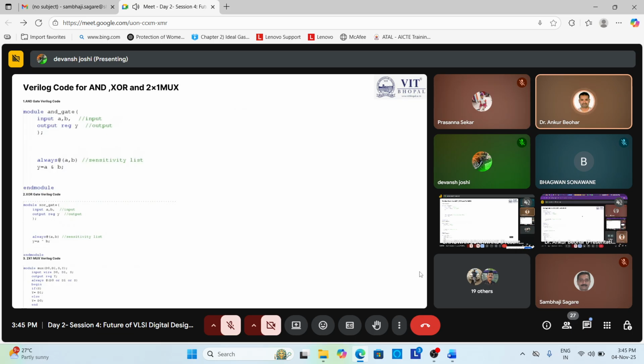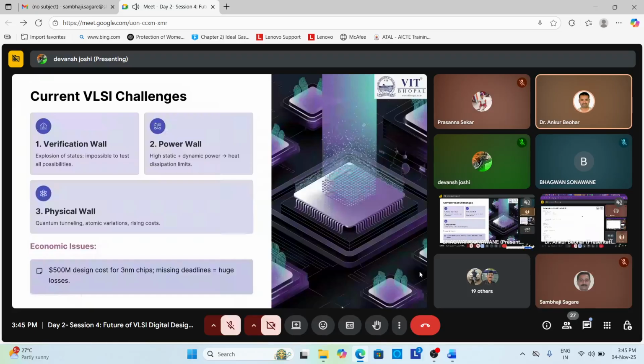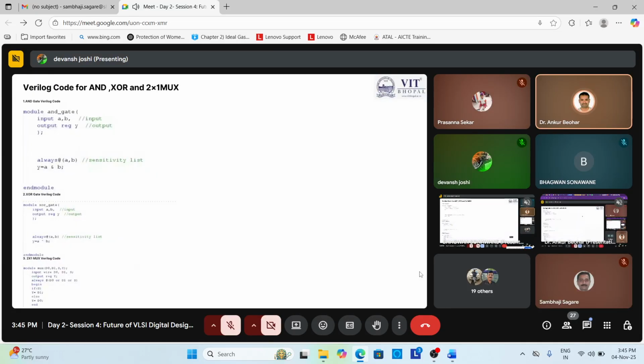So how do we write a sample two-input AND gate? Here you can see we will design a two-input AND gate, where first we have a module declaration. You can see the module we have declared, with the module name and a list of ports, where A and B are given as two inputs. Then we have port directions, which declare whether a port is input or output.